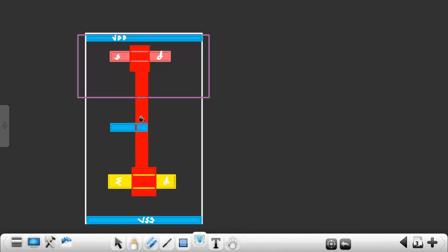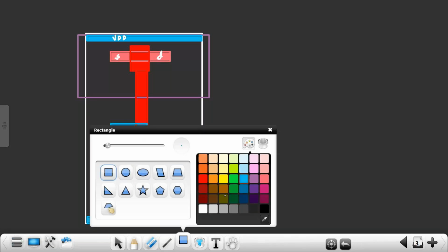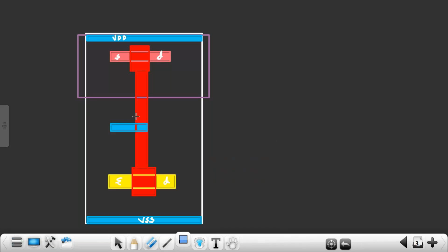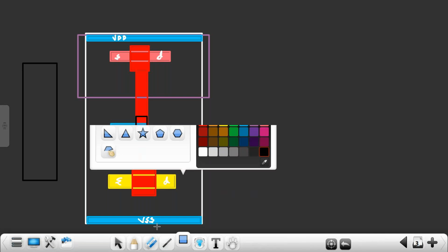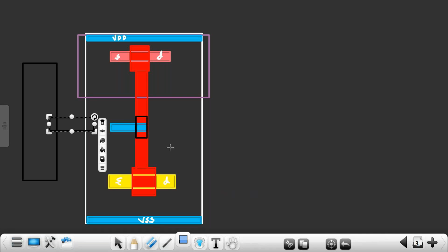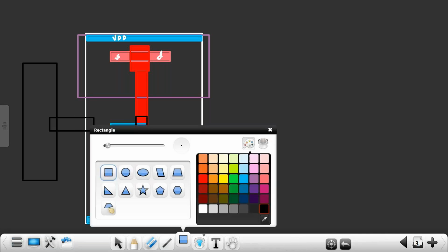Metal is connecting to what? Polysilicon. So I cannot connect directly. We have a contact cut here. This contact cut is used to connect metal to polysilicon. So if I have a previous cell and that cell should connect to this one, it can connect with the metal layer directly now.